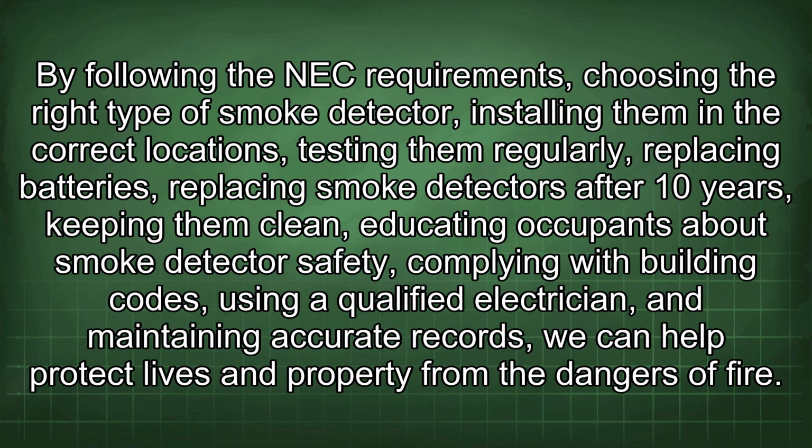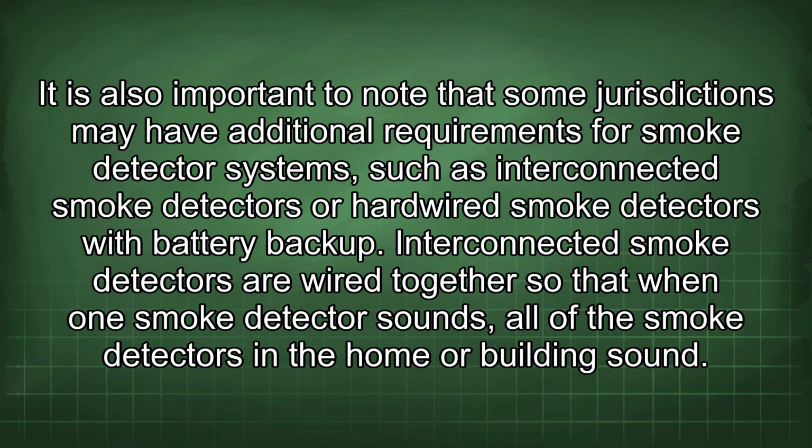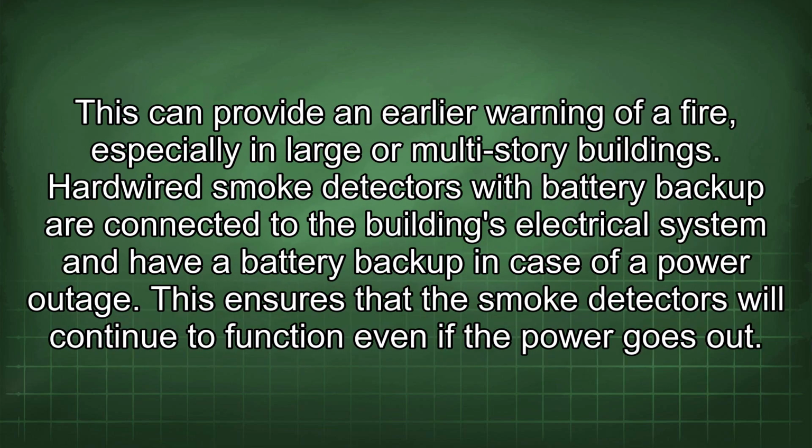of fire. It is also important to note that some jurisdictions may have additional requirements for smoke detector systems, such as interconnected smoke detectors or hardwired smoke detectors with battery backup. Interconnected smoke detectors are wired together so that when one smoke detector sounds, all of the smoke detectors in the home or building sound. This can provide an earlier warning of a fire, especially in large or multi-story buildings.